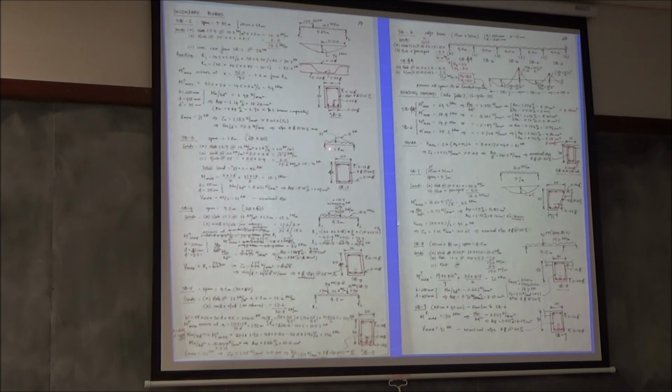So different spans, see the triangular load, the UDL, all these studies were done. Lots of secondary beams. See, you have a continuous beam like this. And then the bending moment diagram, cross section, you have to check at different locations, and so on and so forth. The whole responsibility of the project is on your head. You can share the load. We only gave the foundation to somebody. The rest of it we did ourselves.